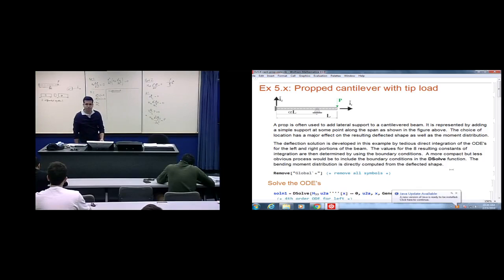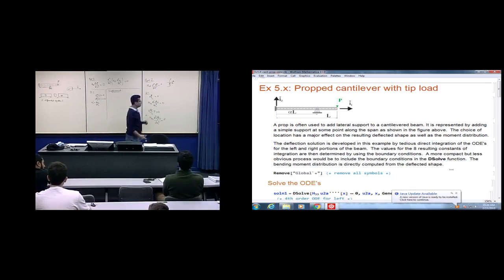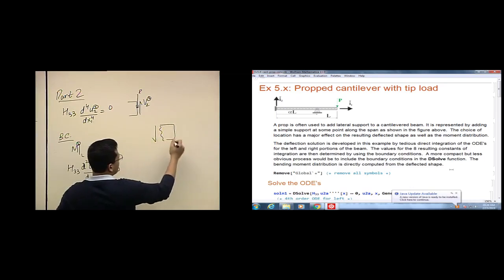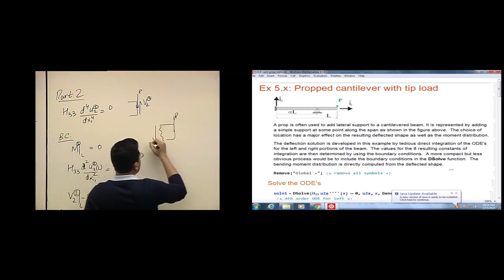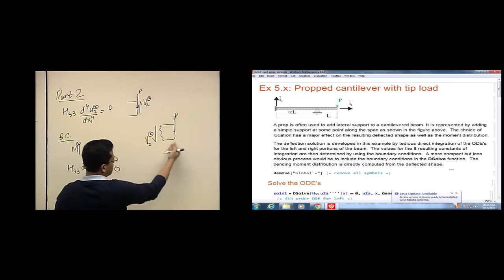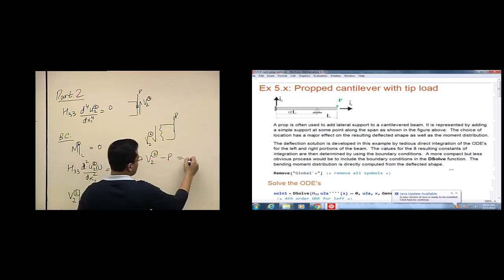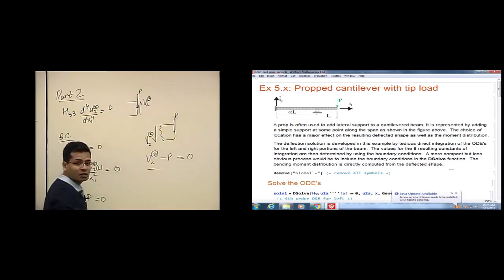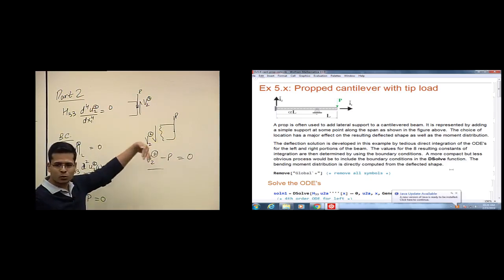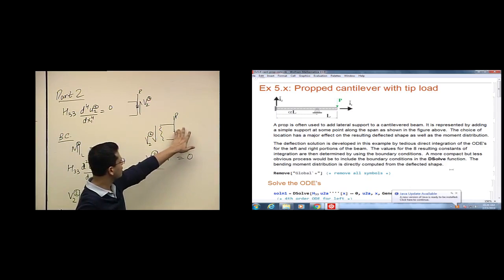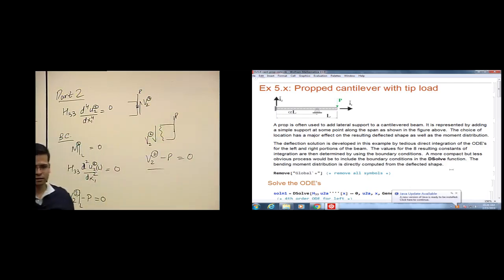When you make a slice for the right part of the beam, you can do the same thing. You have V here, you have P here. So it's essentially the same thing. You will do V2 minus P is equal to 0. So you get the same thing. Okay, because this is positive downwards and this is positive upwards. Cool. Right, so both ways it works.